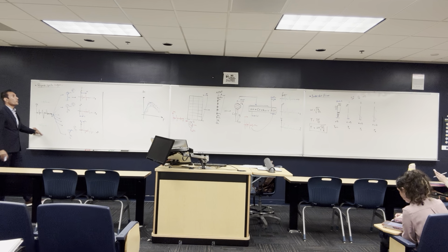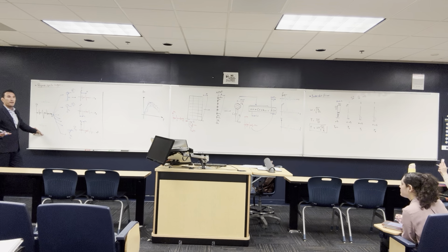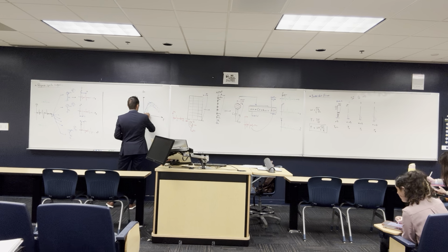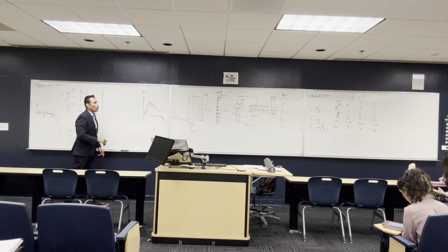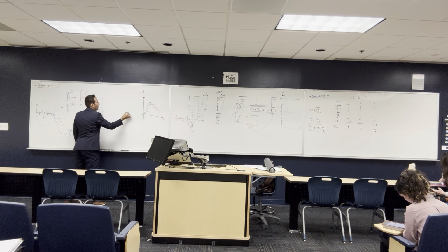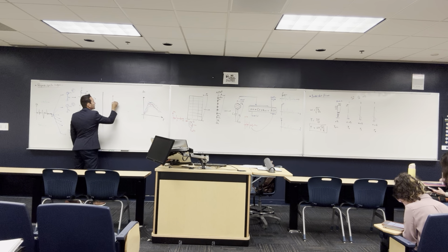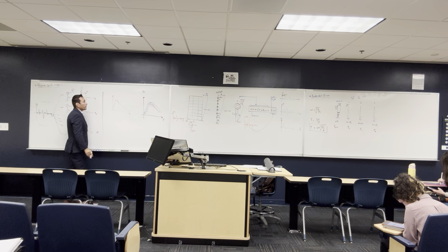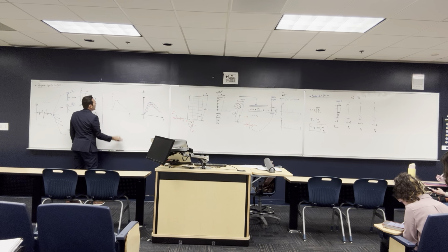And then they had all these curves, but you cannot pick the minimum and you cannot pick the maximum, right? So we usually stick with the mean. So we got something, here's the mean, something like this, and something like this. And they had one single curve, and they call it the response spectrum curve. It's a relationship between the natural period of the structure and the spectral acceleration of the structure. This is a general idea about the earthquake analysis.